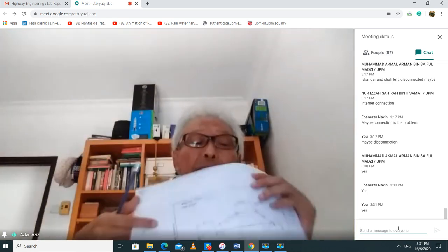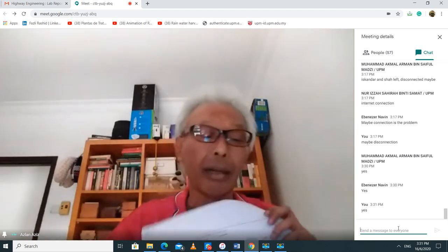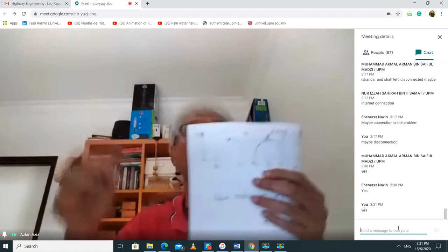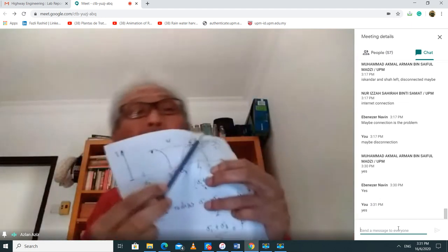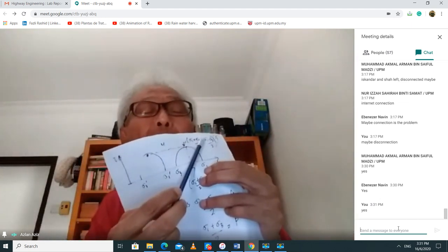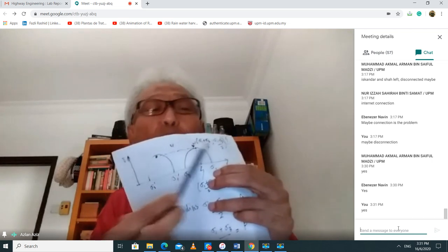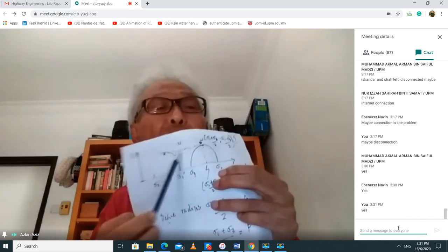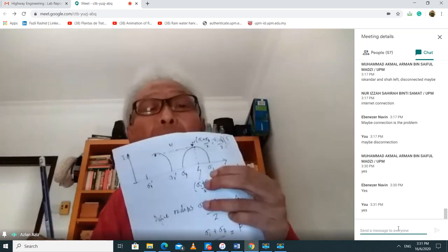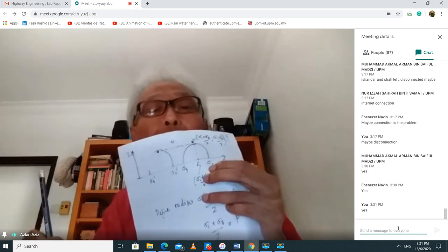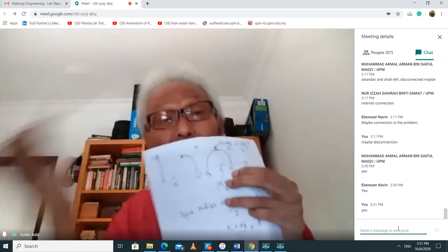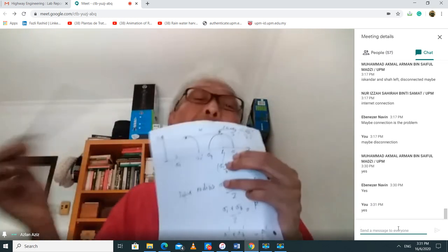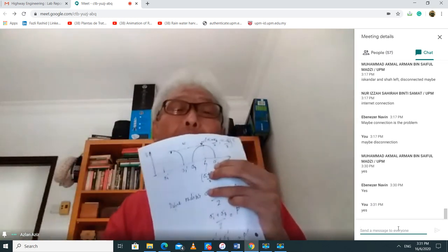Like just now when I say this point here, at the top here, they are related to sigma 1 and sigma 3. What is doing the movement of this point is the sigma 1 and the sigma 3 and the pore water pressure. So if you don't have it in your head, what is increasing and what is decreasing, right, then you cannot follow what I am saying.